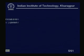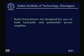converter. Such transducers are designed for use on both hydraulic and pneumatic power supplies. The pneumatic system is operated at an air pressure range of 15 to 30 psi. I am talking about the supply pressure, but the range of the controlled output which we will get from our flapper nozzle system is 3 to 15 psi.